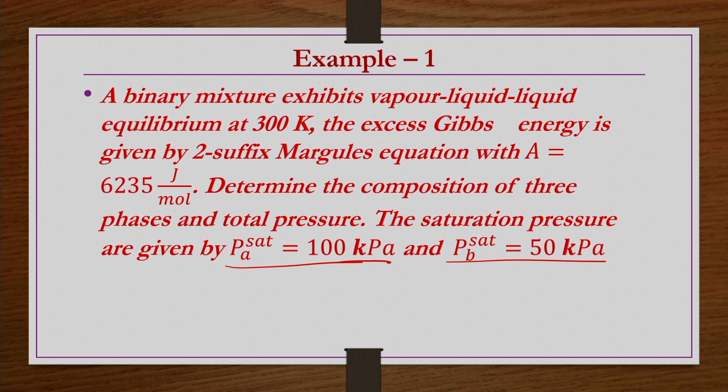So, then we can say that the activity coefficients of this binary liquid mixture can be treated as independent of pressure, because these saturation pressures are low for these 2 components. Then we can segregate the LLE part from the vapor part in the equilibrium relations of VLLE, and solve the equations as we described in the previous slide.